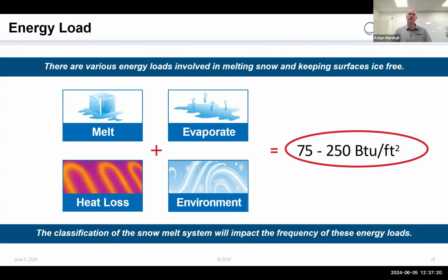And the smart controller now says, well, the app says it's going to start snowing at 6 p.m. I'm going to turn on at 4 p.m. so that my system is ready to receive snow and melt snow at 6. It anticipates, and so it's more responsive. And anymore, even with all those variabilities, snowmelt systems are really, really responsive.